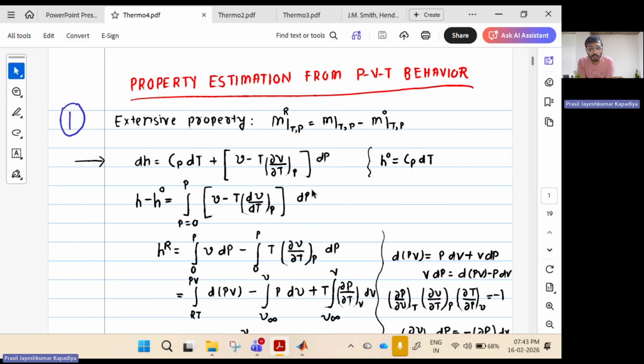That gave us motivation to study the PVT behavior of gases. So we looked at PV diagram and PT diagram. PV diagram tells that volume follows cubic equation of state, among which two roots are significant. Of the volume roots, the lower is liquid volume and the higher is vapor volume. After that, we looked at Peng-Robinson, SRK, RK equation of state.